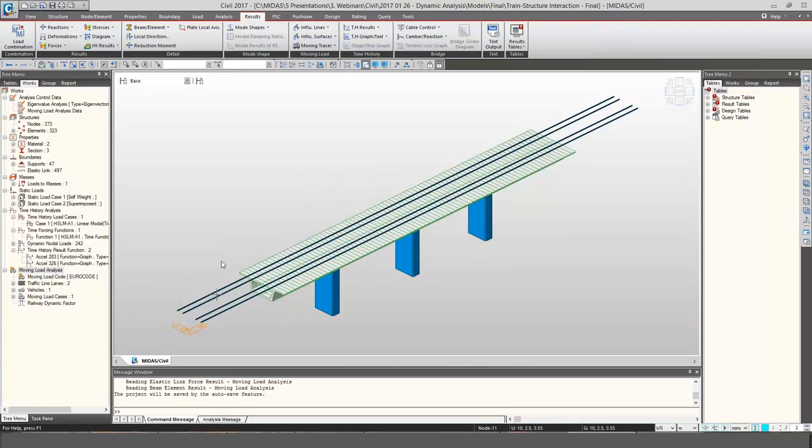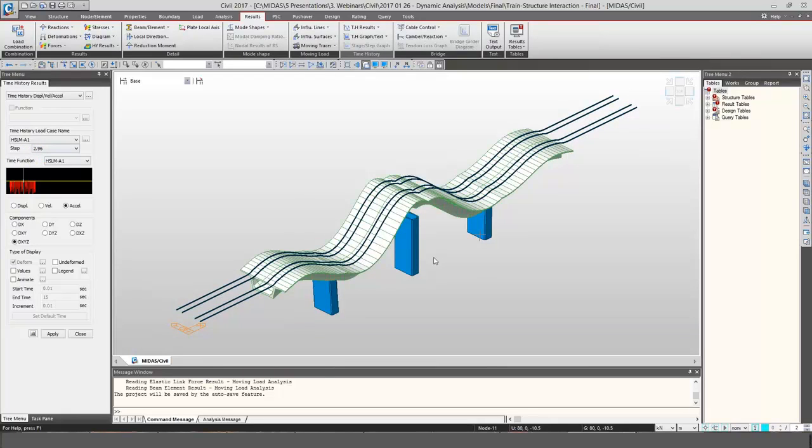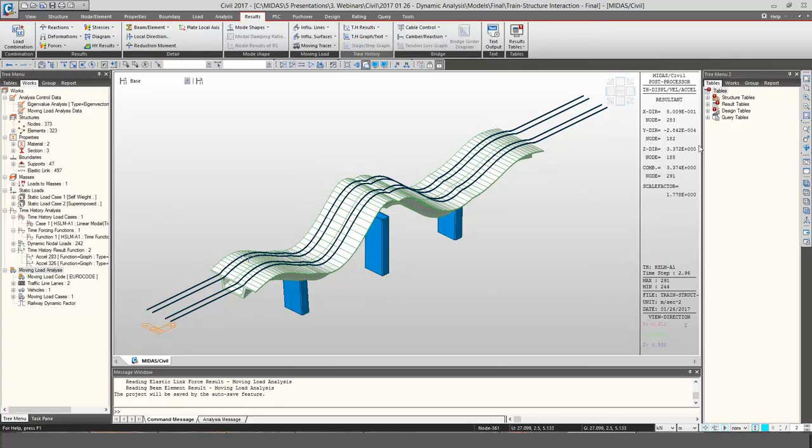And once we've checked these, we can continue with checking accelerations. So checking time history load cases, we can check displacements and accelerations, and we can choose any time step for the time history load case. We can check the shape and even plot the legend. But maybe for this type of check, the easiest way is to actually do it in a graph.